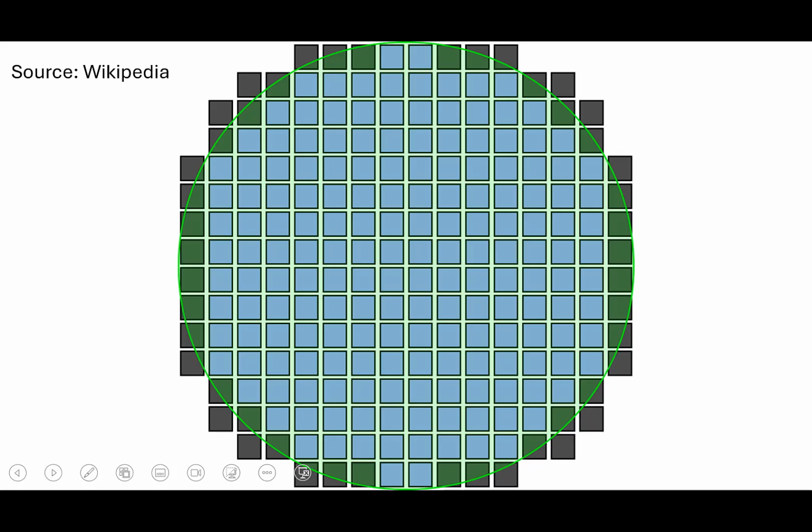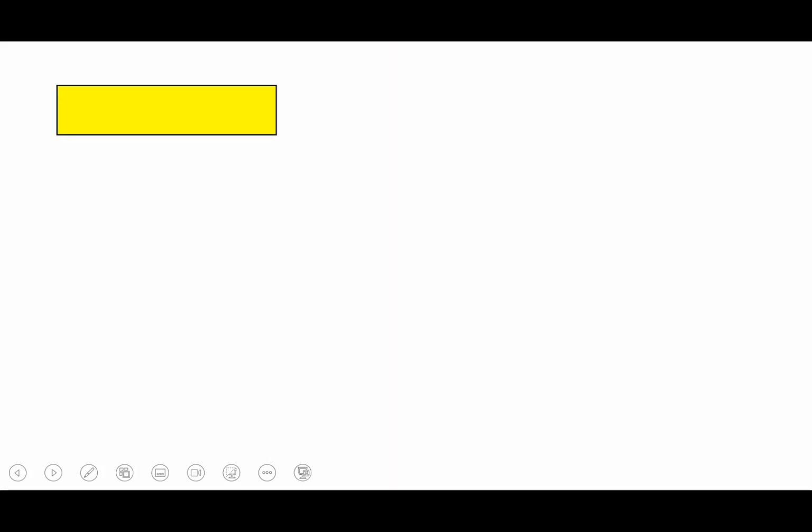Cool. So now let's say I have a silicon wafer like this. Look at one particular chip, and let's say in my design I have a resistor with a nominal value of 1 kilo ohm. Let's say I have another resistor placed close to this in my design. What do you expect its value to be ideally? 1 kilo ohm.